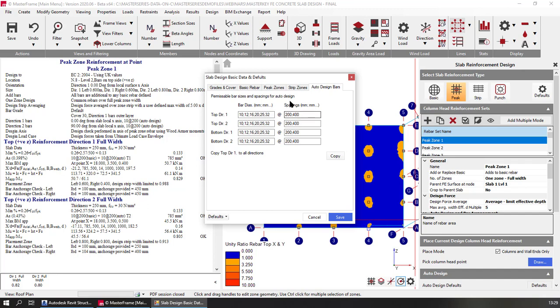To be honest, I would be happy not at 400s but at 100s if you need them, or 200s, and I wouldn't want them at 400. Well, no, we could take 400, of course we could, so every other span, and copy that down to the others. So that's my limiting rebars. Although that 100 is debatable whether you would like it or not, but let's try it anyway.